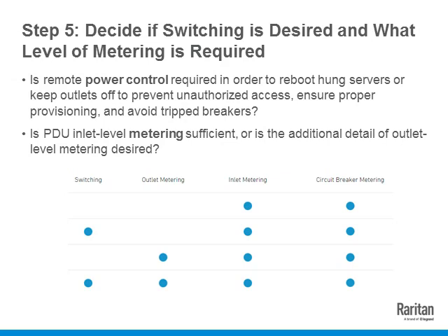What if we can set some thresholds on these so that we can take action as the operators before the breaker trips? Because even though circuit breakers are easier to service than fuses, for instance, you don't need to be looking for a fuse, and you can just flick a switch and reset them, still it has caused an outage. And the idea is to minimize the outage cost by preventing the outage to begin with.